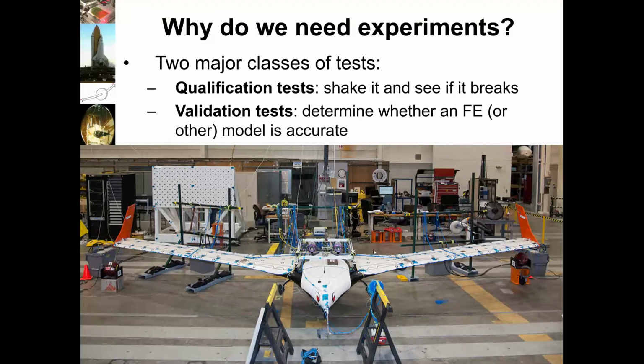If we didn't do this, it could be dangerous because the aircraft can encounter something called flutter, where the aerodynamic forces over the wing cause them to shake violently and can even cause them to be torn off. And so we need to know that the airplane is safe and what speeds we can expect to fly it to. And so this is done by performing a ground vibration test. And this picture shows an airplane with everything mounted, ready for test here. So this is an important kind of test, and this is really what we focus on in this class: having some kind of model and comparing that with the test.